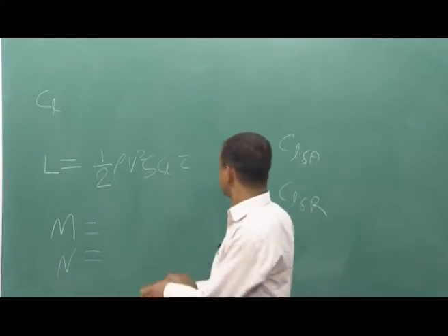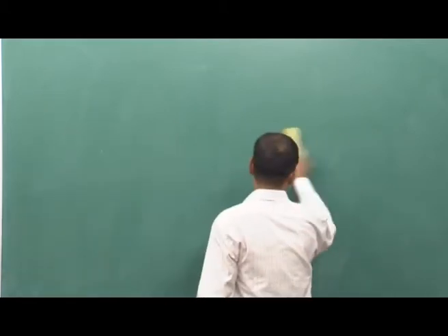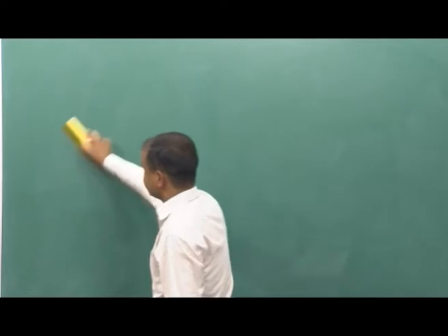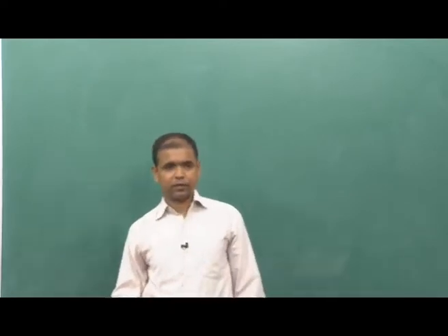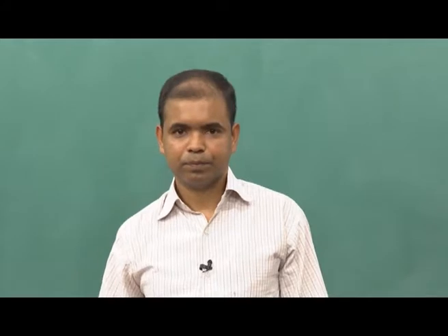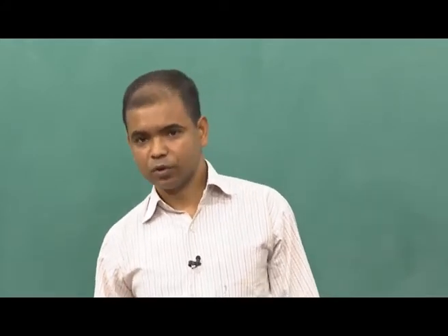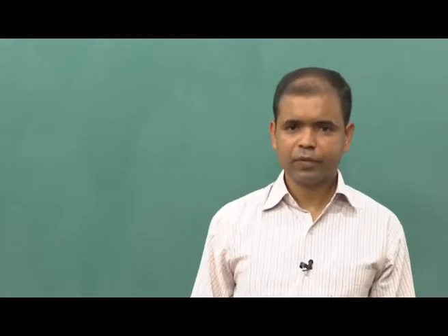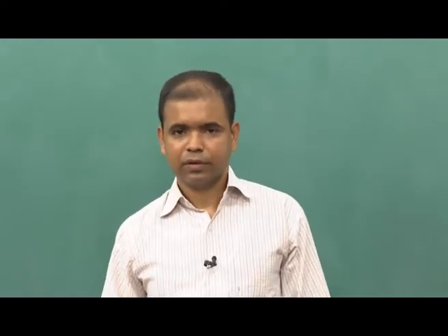Now, the task is to find all other forces and moments acting on the aircraft. What are the other forces? The thrust force and the force due to gravity. In case of propeller aircraft, the force basically depends upon the throttle and the velocity of the aircraft, and if you can model it, you can find it.